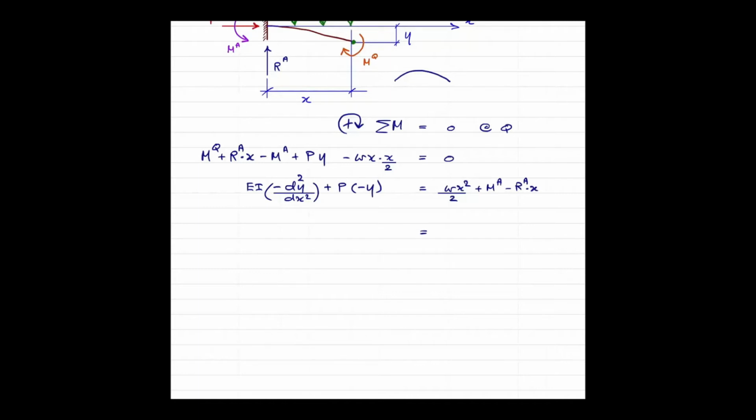So you can see that, oh, well, shear failure came in over here. Well, you can use the theory you learned in RC design, things you have in the code like the ACI, or things you might have seen in publications, in papers and journals relating to structures like concrete or steel. You can predict somehow the failure mode or the ductility of a structure for general cases, or the cases that people have been thoroughly studying.